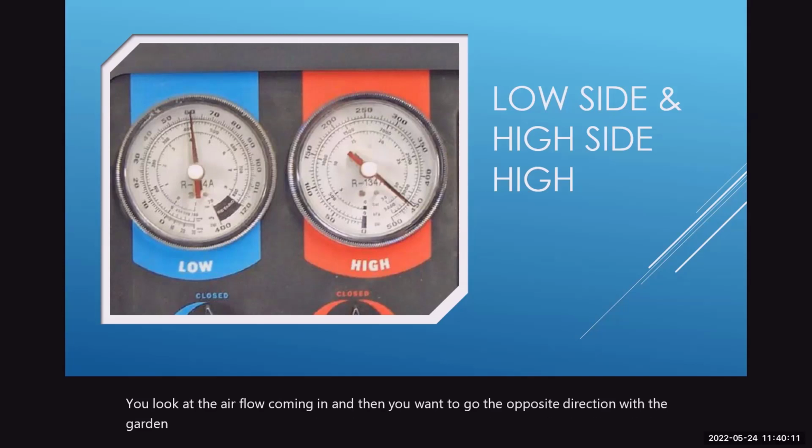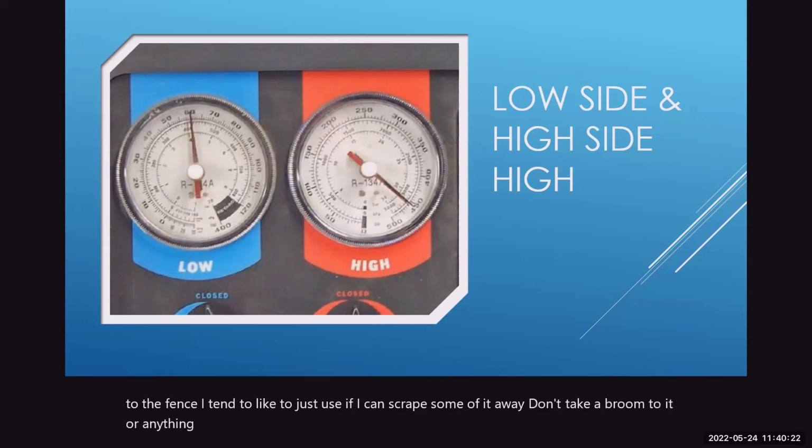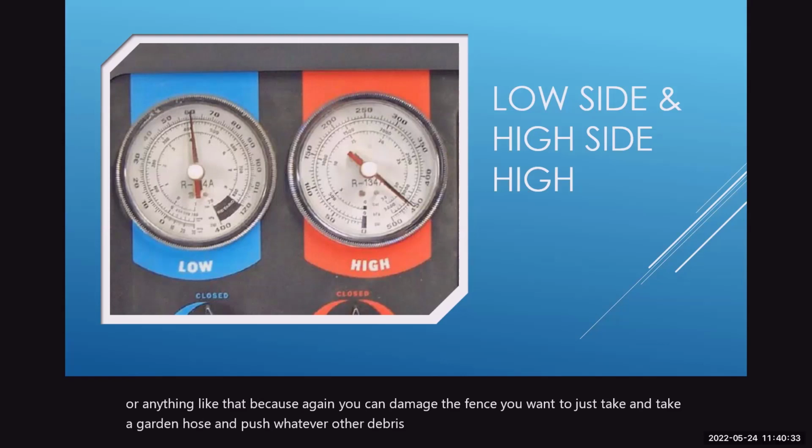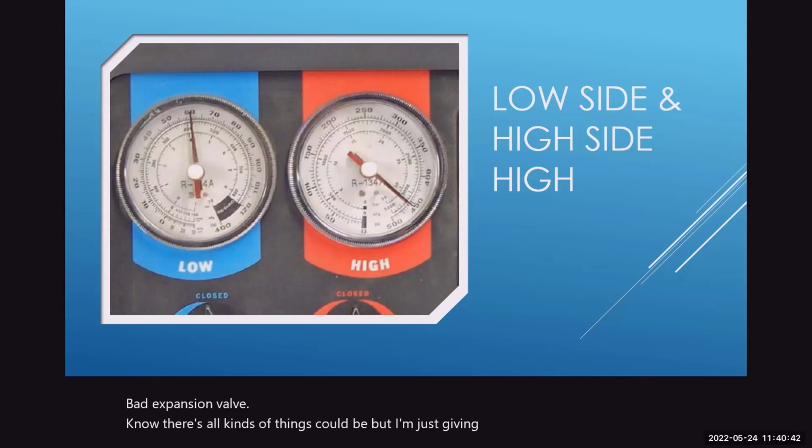You don't want to pressure hose it, because you can actually cause some damage to the fins. If I can scrape some of it away, fine, but don't take a broom to it or anything like that, because again, you can damage the fins. You want to just take a garden hose and push whatever debris out in that direction. We can also have a bad expansion valve. There's all kinds of things it could be, but I'm just giving you some of the basic stuff right now.